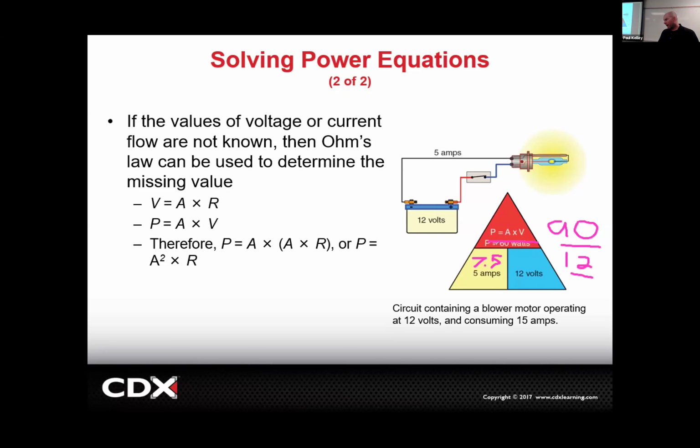What I have seen in the past, though, is they'll do the research and they'll say, yeah, if we bump it up to like a 90 watt rather than a 60, you're still at 7.5 amps. That's still under the 10 amp design. But I've seen cases where the wire, the fuse, everything can handle the Silver Star, but the connection's a little loose at the bulb and the terminals don't fit tightly.